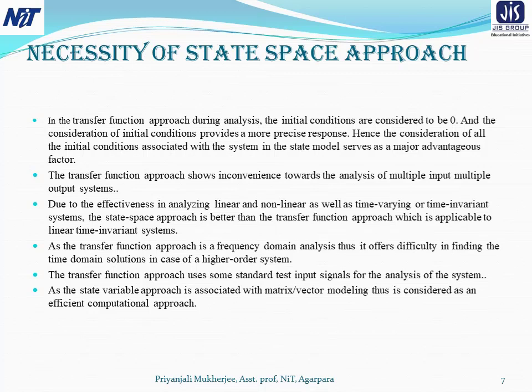Similarly, the analysis gives the system output for a specified input, and no information regarding the internal state of the system can be obtained in the transfer function approach. And it gives the analysis of the system for some specific types of inputs which we have used, such as step input, ramp input, etc. So the state variable approach is associated with matrix or vector modeling, and it can be considered an efficient computational approach.